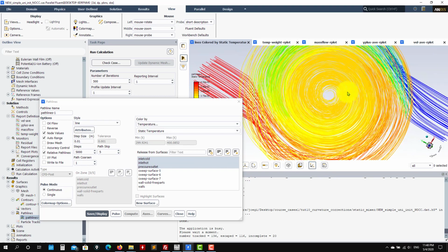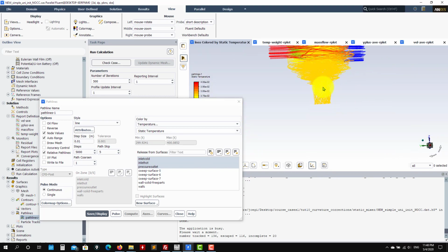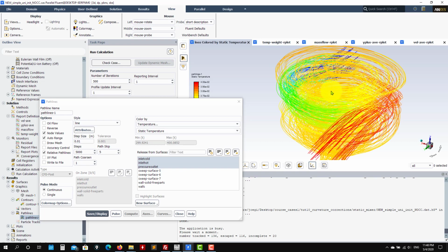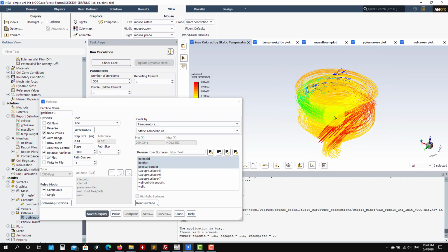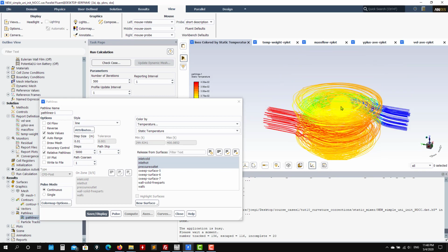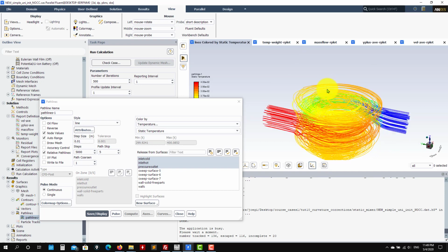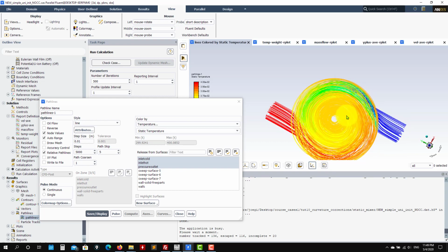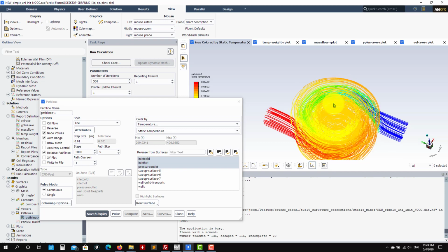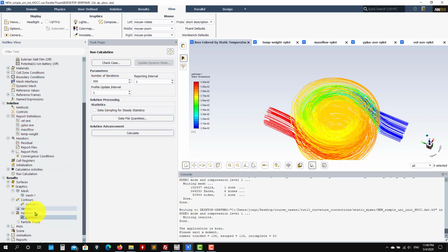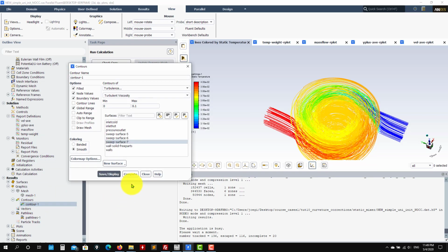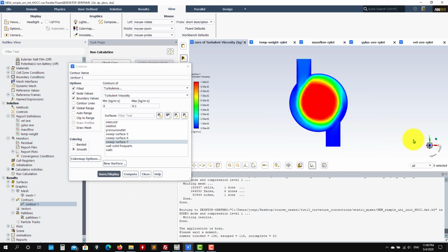So this is very typical. You have it in this kind of application: static mixers, cyclone mixers, or mixing chambers. And the problem here is that sometimes when you have this strong swirl, turbulence models, the classical viscosity models may give you problems, and this curvature correction will take this into account, so it will try to generate less turbulent viscosity.